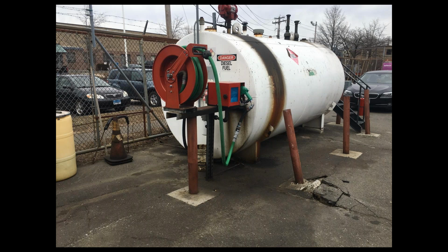Remember, I talked about general containment. So you also have to address spills from that transfer area with the hose, filling the tank, because it might result in an overfill, which obviously occurred here, or depending if it's cam locked, you could push the product out the vent. So you may have to build some form of containment. It's general, so you size it. And it may be something that you can implement using a spill kit, but you have to address that.